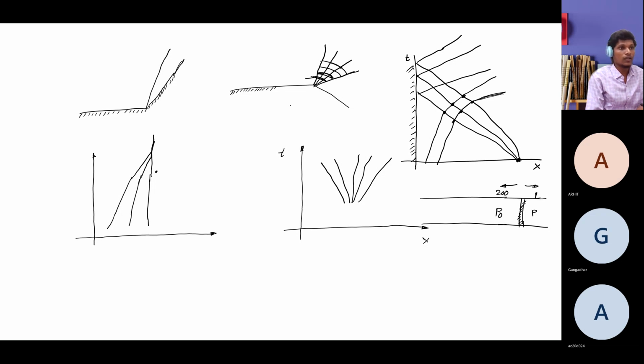So how you can draw this? Because I can say that the professor gave you an overall view of how these expansion waves and oblique waves work, but not in detail or the detailed mathematics of it, right? Don't get confused with backward direction. Even if you are converging at this point, if you draw in the backward direction, it won't create any oblique shock wave in the flow field. You always need to see only one thing, which direction your flow is moving. Your flow is moving in this direction, right?